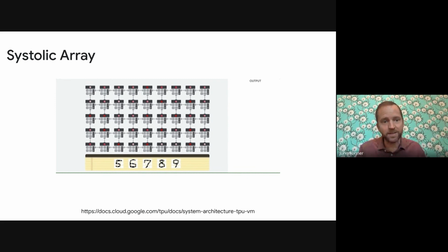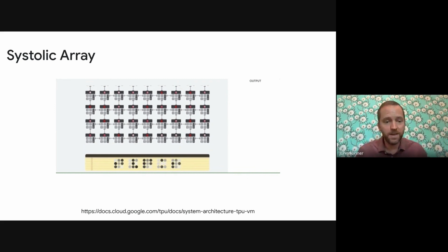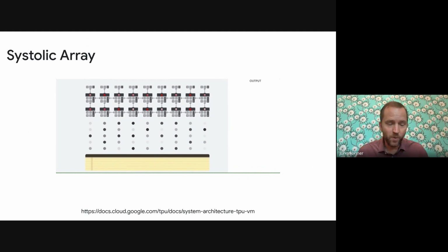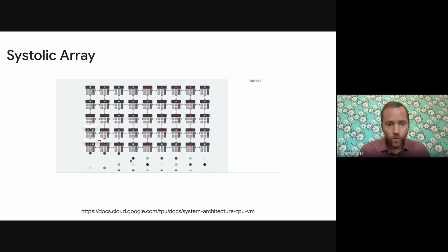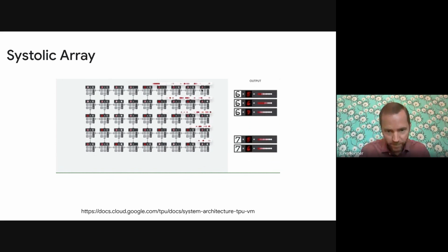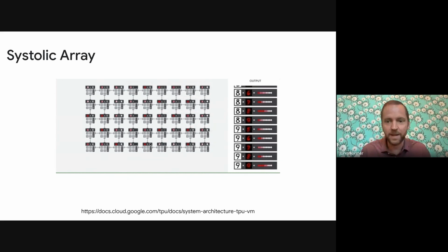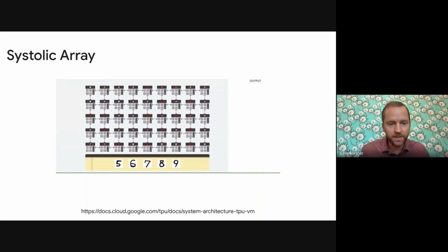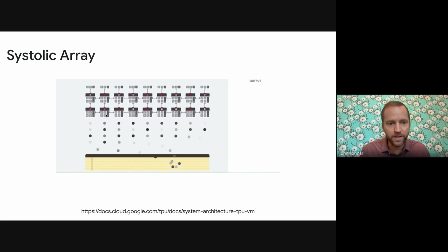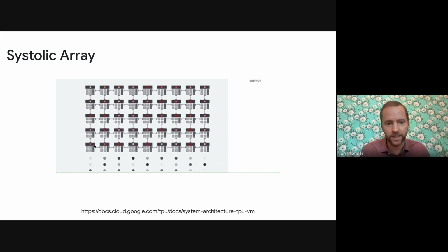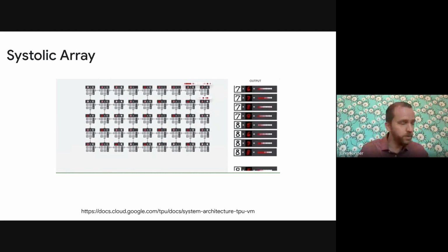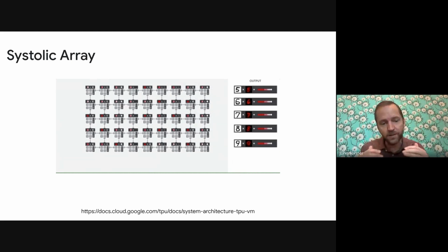Let me talk about the systolic array. So within the matrix units, the way that these are orchestrated, when doing these matrix operations, it's not required that they all perform the same computation at the same time. Usually, unless you're this bottom left guy here in this image, to be able to do the operation that you want to do, you need the output of your neighbor to the left or the neighbor below you. And so the TPU specifically handles data flow to be 1 clock cycle shifted.